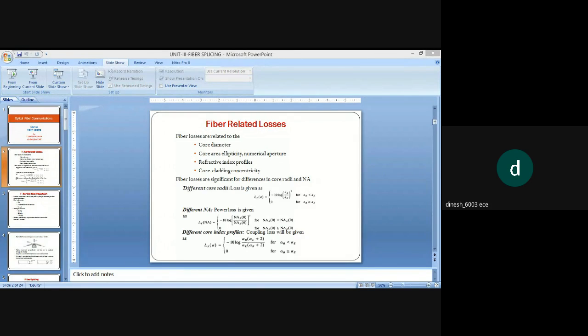This requires careful control of the curvature and the tension. The fiber should be tightly tensioned or grabbed in such a way that the scoring blade will cleave away the optical fiber.